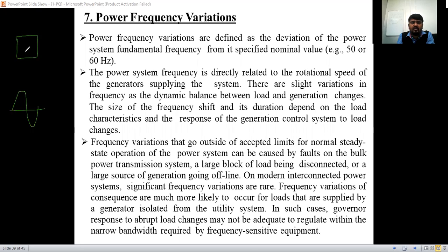The synchronous generator we are using? Yes or no? The generator we are using here, whatever the shaft is rotating here, if it is one rotation, it is called one cycle. That is one cycle. Yes or no? It completely depends on the speed of the generator. The frequency will be different and changes here. If the speed is constant, then the frequency will be constant.